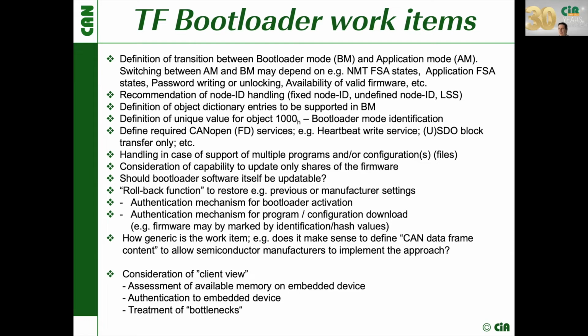We are evaluating later on whether we can increase the openness also for other CAN-based higher layer protocols. But at the moment, this is the main focus, CANopen and CANopen FD. We are discussing the node ID handling, but it's difficult to find a recommended solution because, as you have seen in the use cases, there are good arguments for any use case to use the fixed node ID or undefined node ID, take that one from the application, or to use